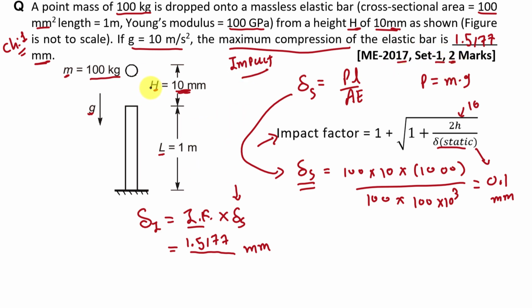So from here we have to understand that the load by this mass will be impact load. So here we have to multiply this deformation by the impact factor. Fine.